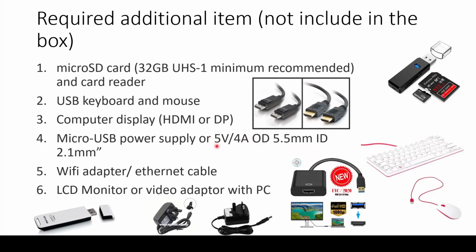So you must specifically use a 5 volt 4 ampere adapter in order to power on the Jetson Nano if you want to use the power supply. And then there is a configuration to it that you need to look into.